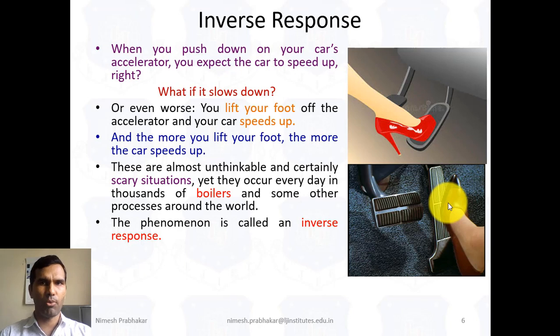Inverse means opposite type of response. Here we try to increase the speed, but the car speed is decreased. But when we try to decrease the speed, the car speed is increased. So the opposite effect occurs, and this type of phenomenon is known as the inverse response.